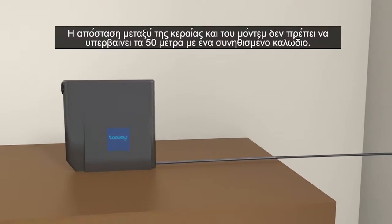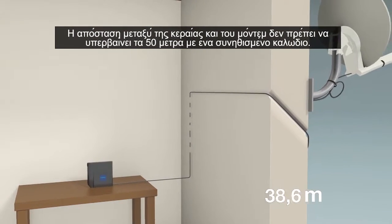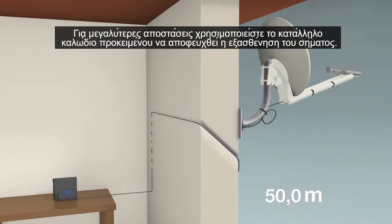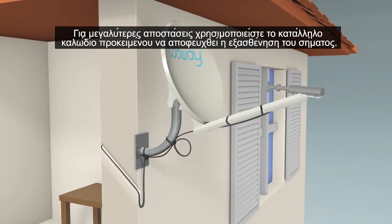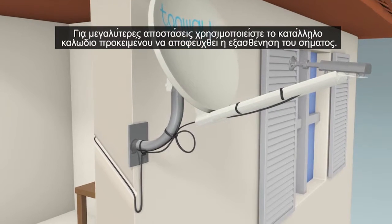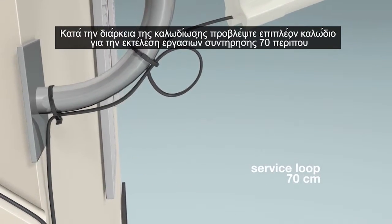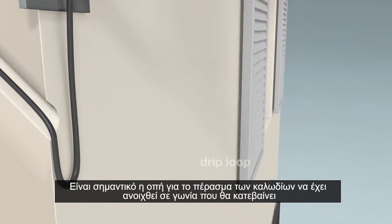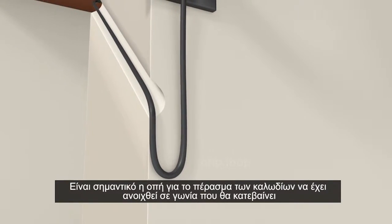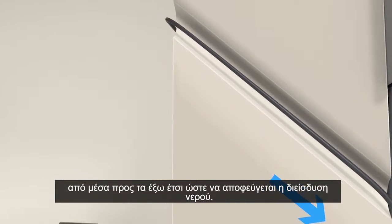The final criteria for choosing a good installation position is the cable distance between the modem and the antenna. Using standard cable, the maximum distance is 50 meters, but can be longer depending on the type of cable. When cabling the antenna, leave a service loop of about 70 centimeters to enable the replacement of connectors. At the point of entry to the building, put in a drip loop. When drilling the hole in the exterior wall, drill down at a slight angle to prevent water penetration.